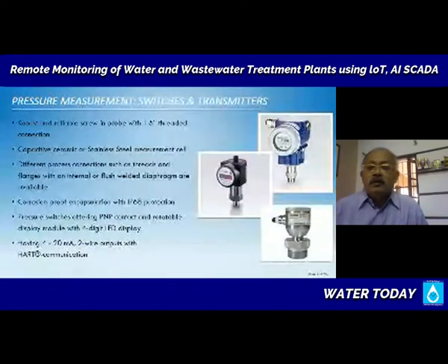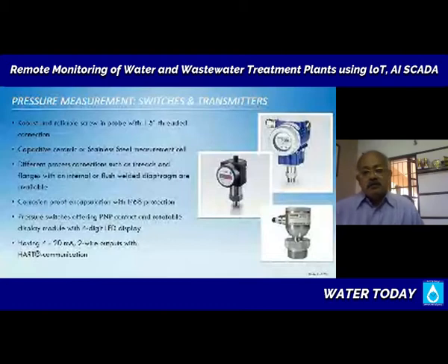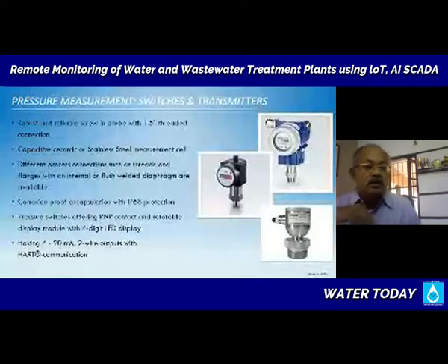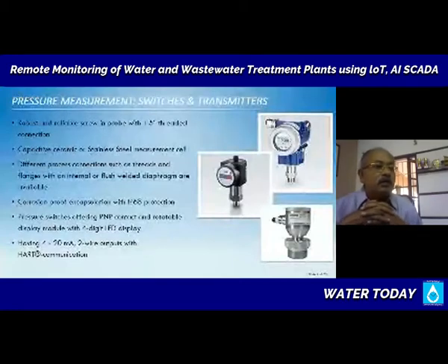So it is an important parameter, to maintain pressure at least at the farthest points in the network. Now, one other thing in terms of measuring pressure: if there is a breakage in a pipe somewhere, you will have telltale evidence, which is loss of pressure. So if you are monitoring pressure in your water network, and between 2 points you notice a pressure drop, then you could imply that there is a broken pipe somewhere in this area. This is why pressure is quite extensively monitored in water networks.